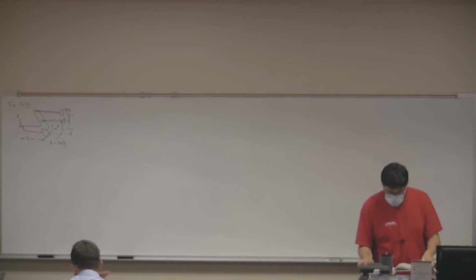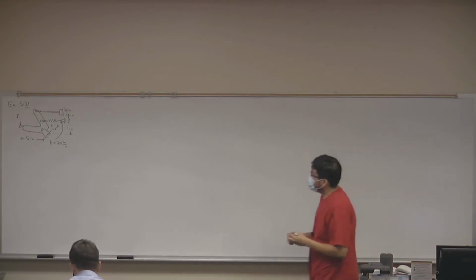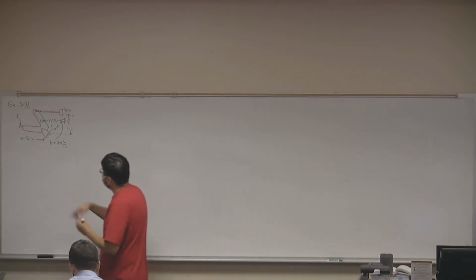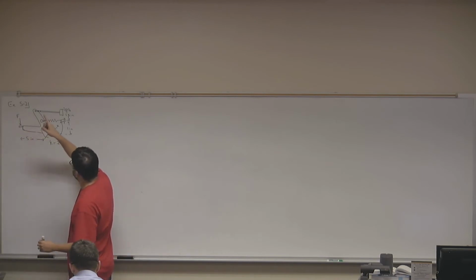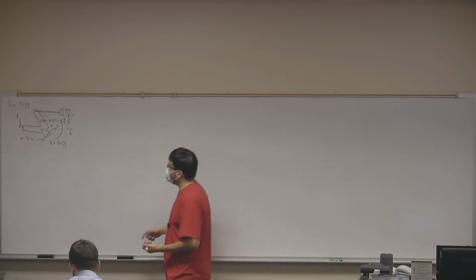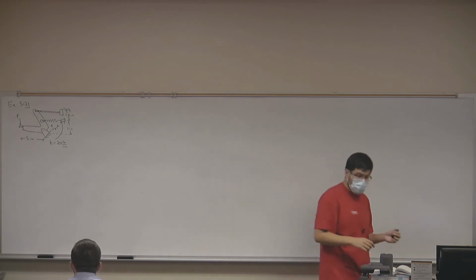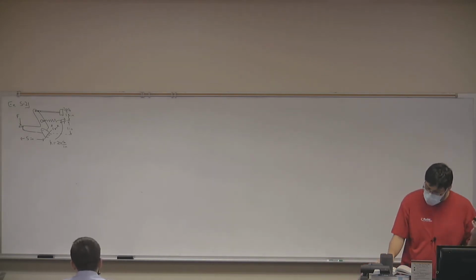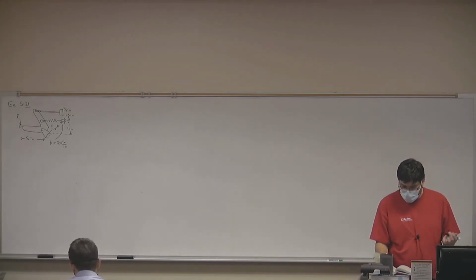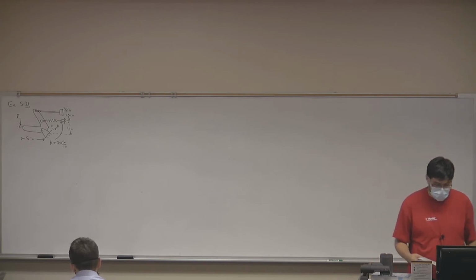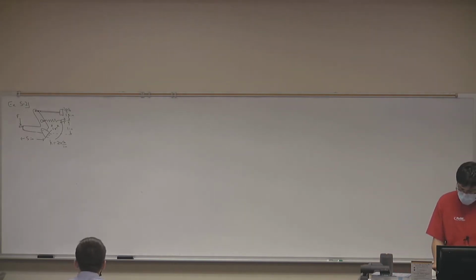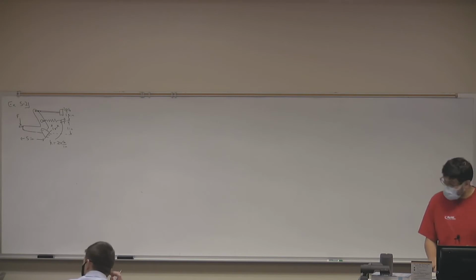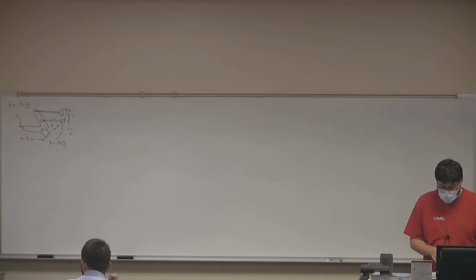So we have what's essentially a system with 1, 2, 3 forces, and however many reaction forces we can find. Now this system, of course, let's say that we balance this. This system, if we want it to be balanced, has to have the sum of the forces and the sum of the moments equal 0.